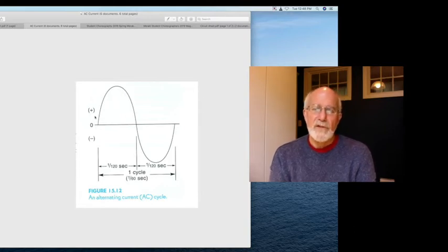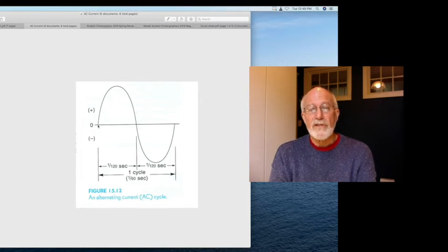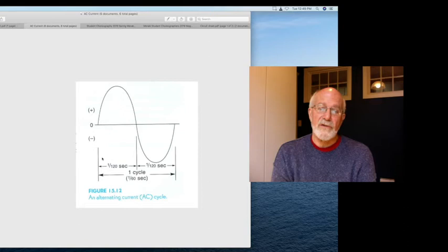So you don't need to understand this accurately, except what you do need to grasp is that the current starts flowing, it increases going in one direction to a maximum, tapers off, crosses over at zero, goes the other direction to the same intensity, and crosses over again at zero. And it does that in North America every 120th of a second. It's reversed, it's a half cycle. And in other systems, it's 100th of a second.